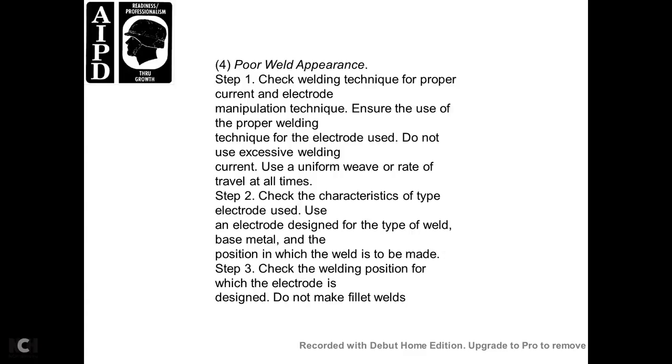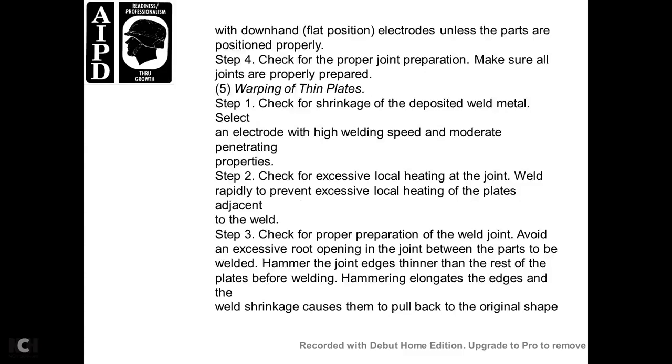Step 3, check the welding position for which the electrode is designed. Do not make a fillet weld with a downhand flat position electrode, as you cannot fill the joint properly. Step 4, check the proper joint preparation. Make sure all the joints are properly prepared.